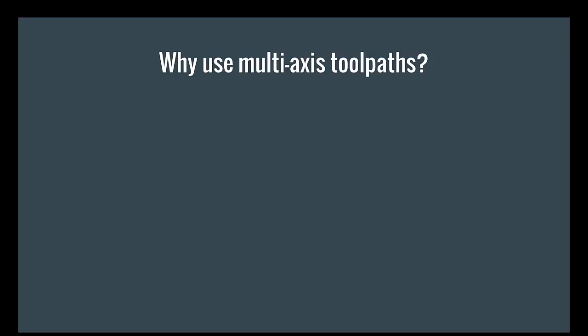Right. I think that hits it exactly. What are the right cases to use it, and when should you use it? There are quite a few different answers to that. Let's just go into it. My first thing would be: don't. Unless it has advantages, don't try to just shoehorn in a multi-axis toolpath because, like Tim said, you have this fancy 5-axis machine and you need to use it.